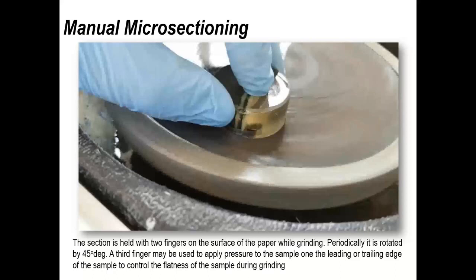And ideally, I'm trying to control that right across the length of the microsection, because if you're going to be cutting up 20 joints, you want to see all 20 joints with the same depth of grinding. You don't want some that are bigger than others. You want to control that. And you can do it with time and care manually. You can do it more easily automatically, but with both techniques, you can screw up if you don't do it properly.